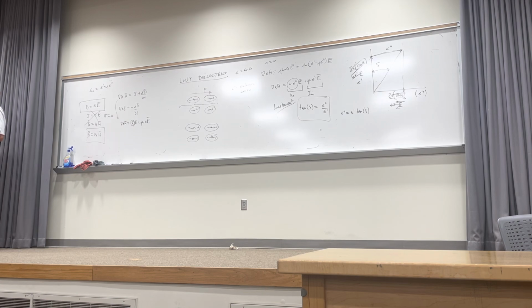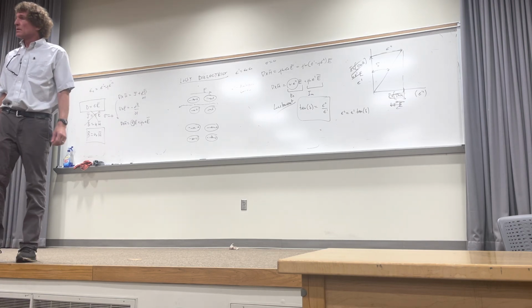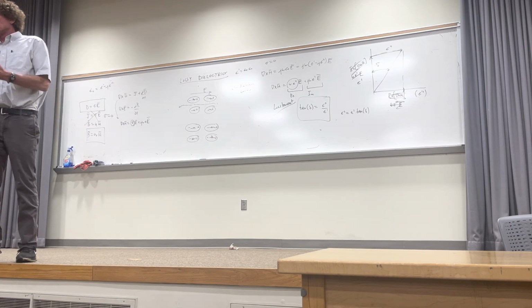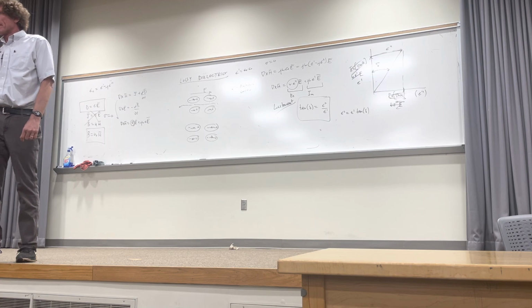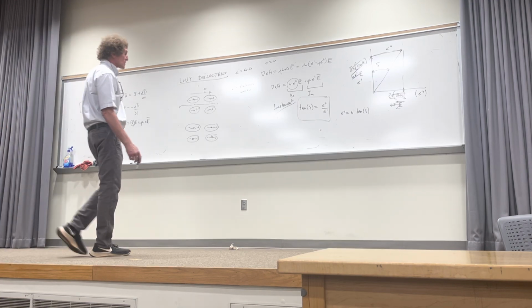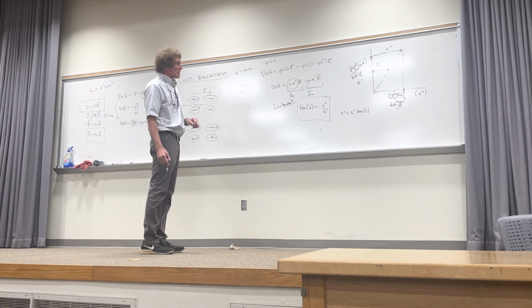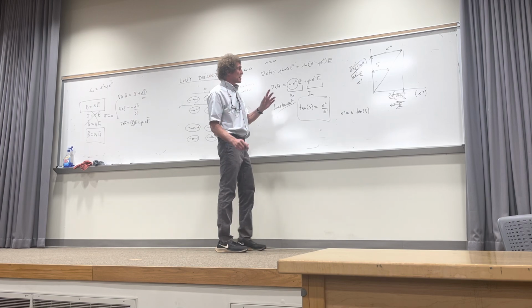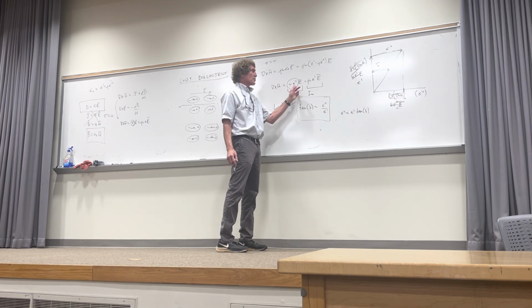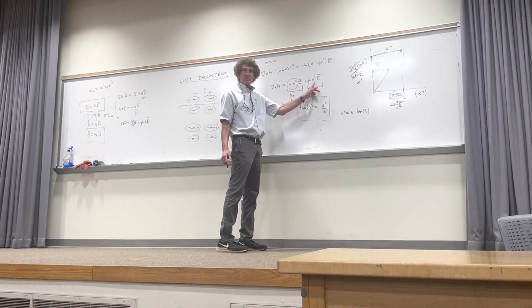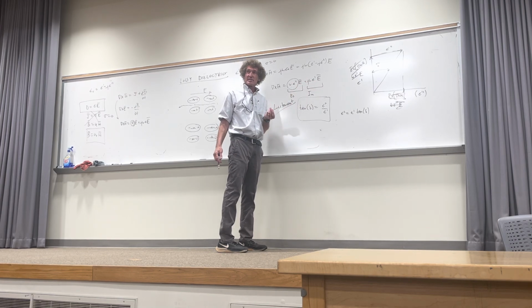Just one thing: for epsilon double prime, will units still be in farads per meter? Well, they have to be the same units. Will epsilon double prime be given as a coefficient value like an epsilon relative, and you multiply that by epsilon naught? Well, let me back up here. The units of epsilon are epsilon single prime minus j times epsilon double prime. So this unit would be farads per meter, but with a j complex.